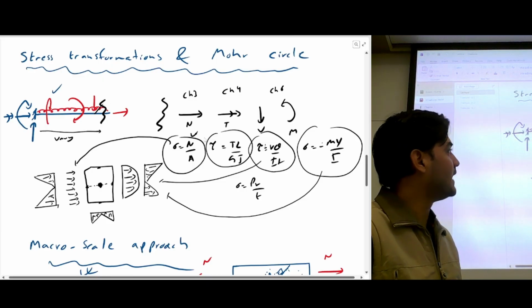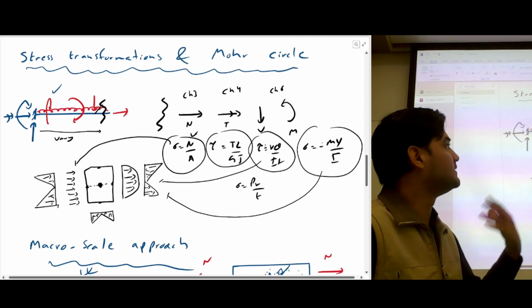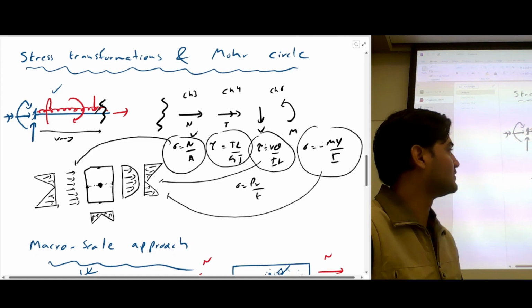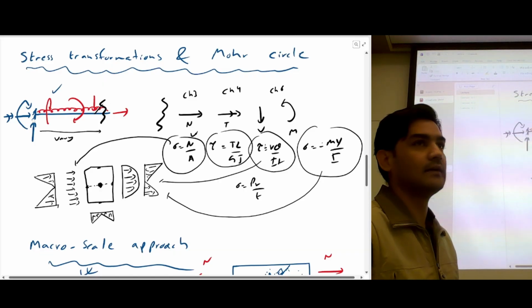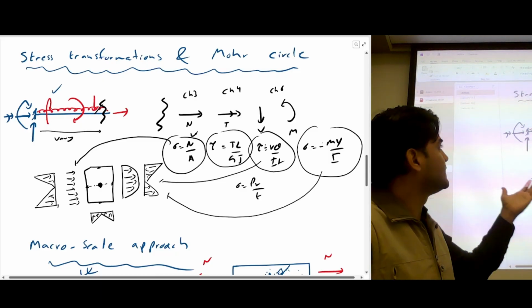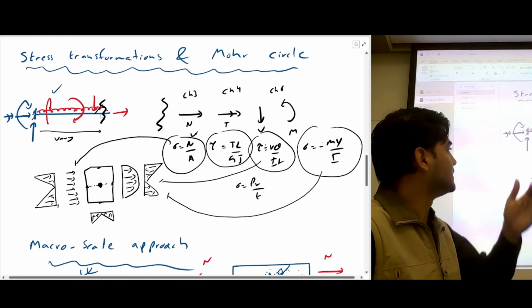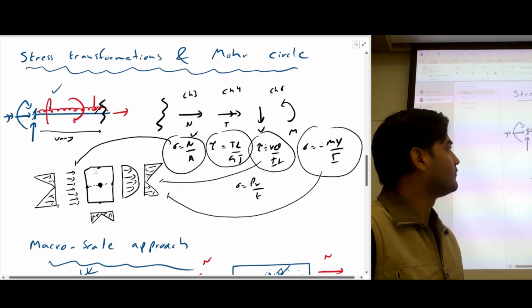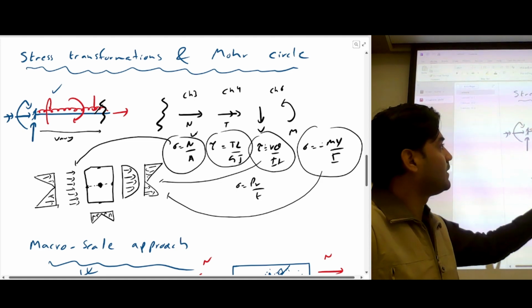So you will have a bunch of different stresses, and these stresses, we talked about on Friday, are not constant always. So for example, it's reasonably assumed that normal stress is going to be constant throughout the cross section, but that is not true with the shear stresses, with the axial stresses because of the bending moment. It is also not true for the torsion stresses as well. So you can already see it takes a little bit of work to figure out, because normal stresses maybe are constant throughout, but torsion is different along the cross section, shear forces are different, bending moments are different along the cross section, also stresses are different. So if you have to figure out the combined effect of all the stresses, you need to do a little bit of work. So that's where we can get the maximum stresses.